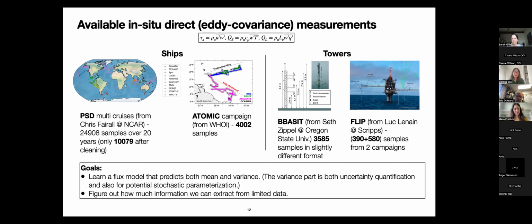But also, I have seen technical documents from Chris Farrow where they document how there is uncertainty associated with your averaging time window. So depending on if you average for 10 minutes, 30 minutes, or 1 hour, there's sampling uncertainty that gets reduced if you average for longer. So that's related to your processing.